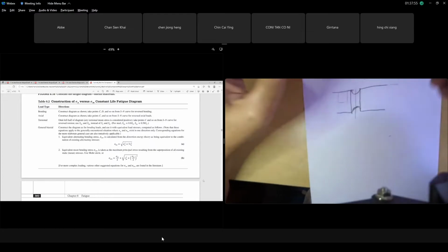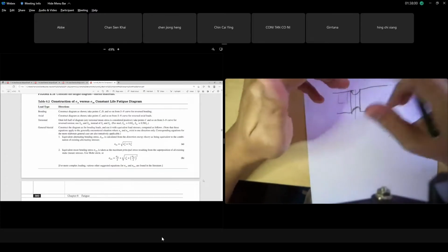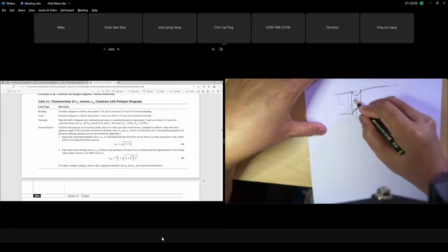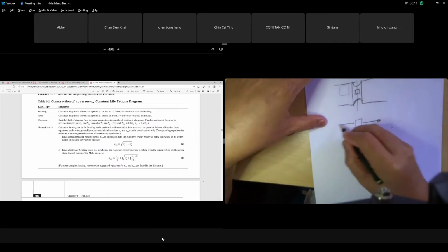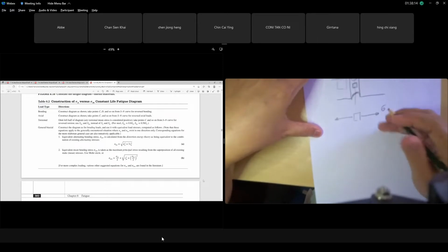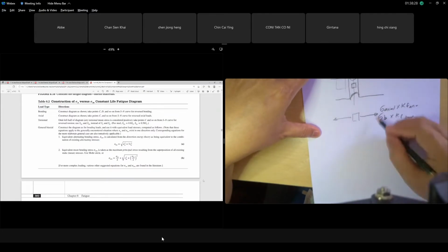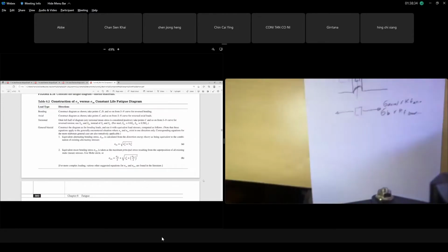Okay, for the groove, kita punya case here. So we already have KF axial, kita dah multiply our axial stress with KF axial. Our bending have multiplied with our KF bending. So our element here, since we don't have torsion, we have sigma axial and we have sigma bending. Nampak tak? This one already times KF axial, and this one bending times KF bending just now. So we add it up together. So your element only has one direction.